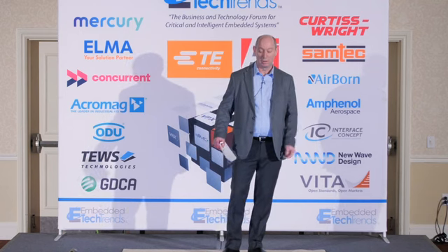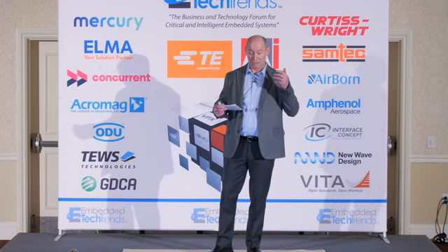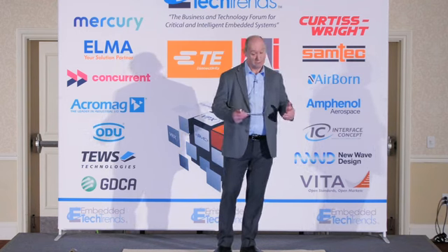But then SOSA came along with the goal to hit the panacea of plug and play for VPX, and really solve this interoperability problem. So SOSA defines a technical standard from a systems perspective. It obviously covers the hardware, and from a hardware perspective, it tightens up the OpenVPX spec by limiting the slot profiles for plug-in cards, standardizing the mechanicals and the cooling, and tightly defining the connectors and the interconnect protocols. But it also defines the chassis and backplane and other infrastructure, tightly defining the backplane requirements, clock topology, and also things like chassis management.